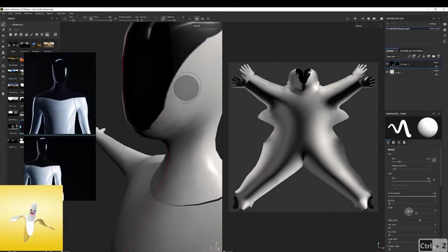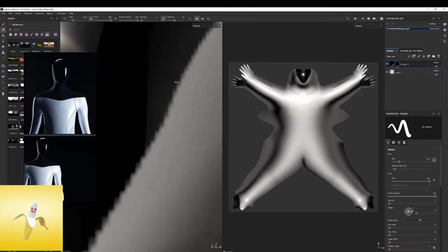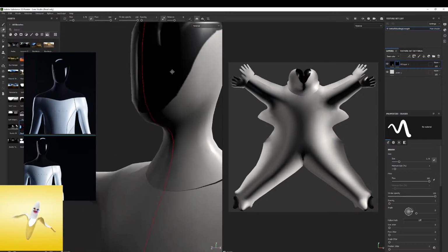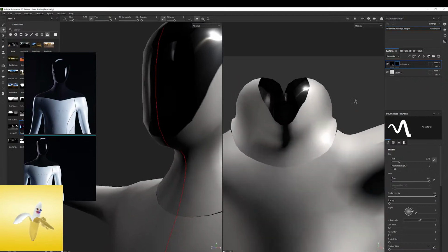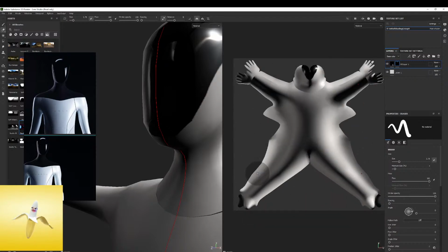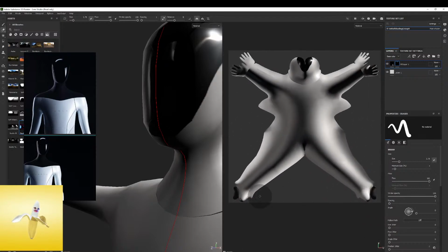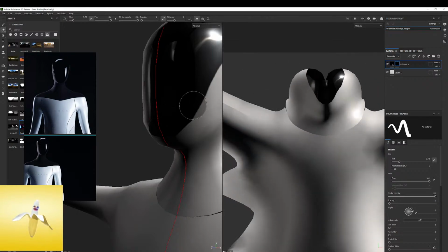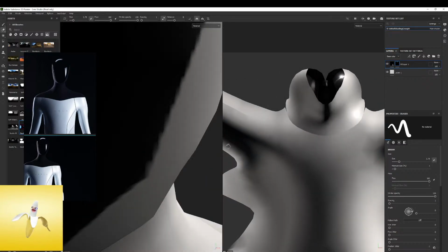All right, so I'm going to get in a little bit closer here and smooth out these bits on the edges. And I'm noticing some aliasing happening. Aliasing happens when your UV space is not high enough resolution. And the UV space is this. You see how the texture that applies this paint makes up a very small percentage of this square. This square is the UV tile. You got the U axis and the V axis, UV. And in that UV space, only this many pixels were dedicated towards the mask, which is why we're getting the aliasing and the pixelization around the edges.